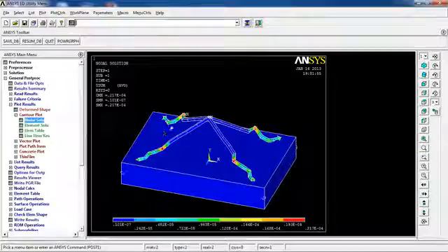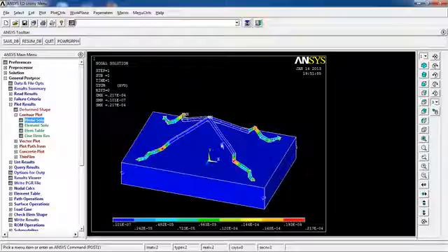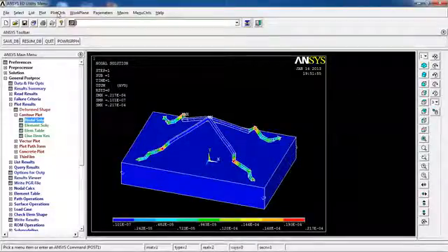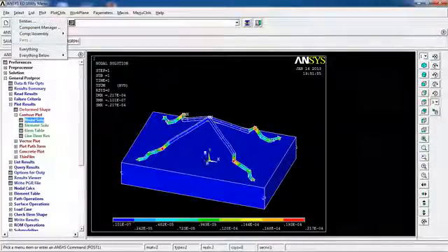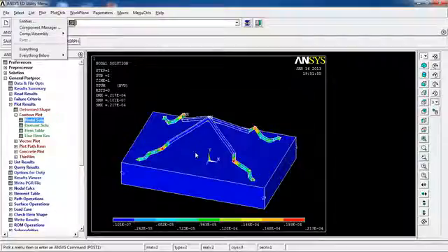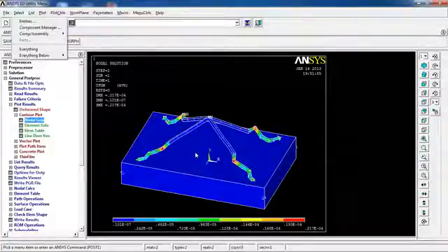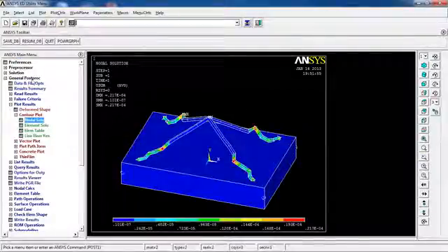The reason that yesterday I didn't see this 3D representation was that I came to select entities and then picked the key point in the center and then the node there, so I had only one entity selected at a time. That's why ANSYS didn't show me this 3D representation.